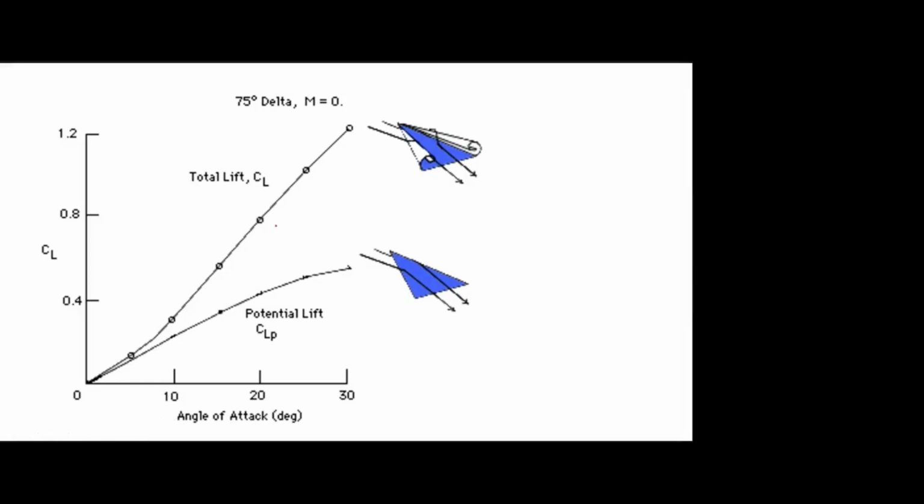So here they explained, if there are no vortices and you find the lift, it will be like this CL distribution, and because of the vortices on the wing, the CL goes here. Then this region is the vortex lift. This is the normal lift produced by this wing shape. This additional lift is produced by the vortices. So this is the vortex lift. Is that clear?